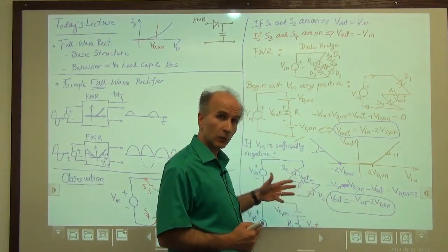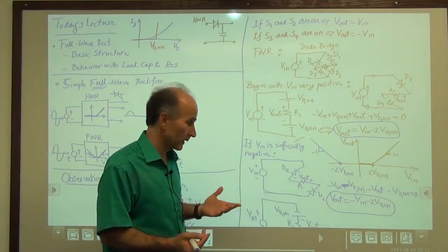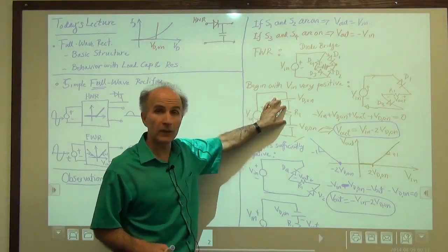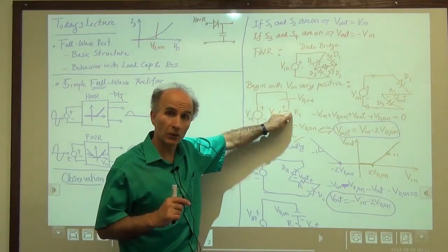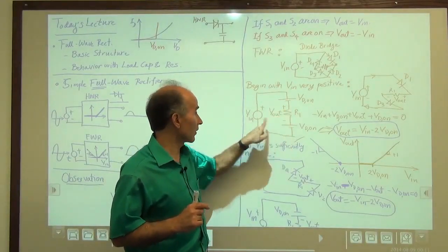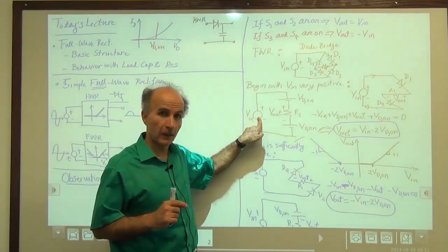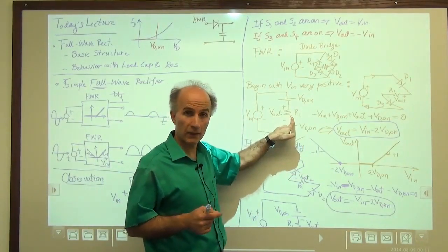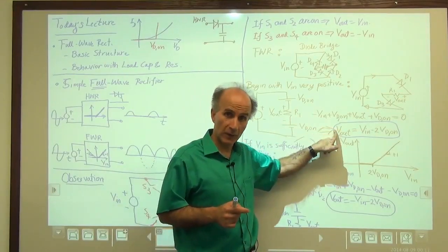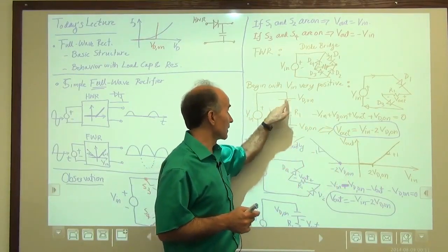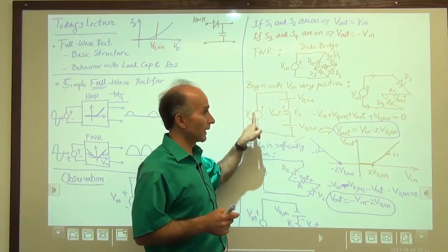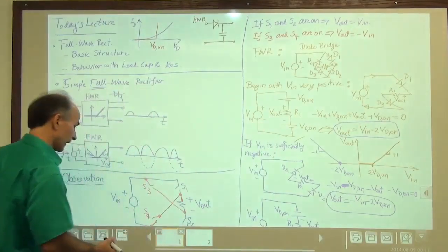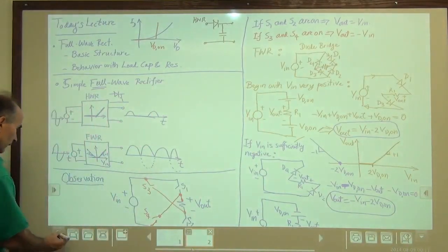We can see that this would hold even if we have a capacitor. What the circuit does, the way it delivers this voltage, is independent of this load, as long as these are ideal voltage sources. You notice from the KVL that we wrote that there was no role for R1 in this circuit. So even if it's a capacitor, it would be the same thing, provided that there is a voltage source here, there's a voltage source here, and there's a voltage source here. So keeping that in mind, we can go ahead and analyze the circuit with a capacitive load.